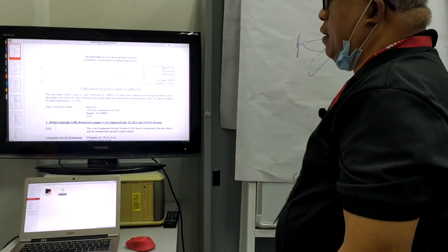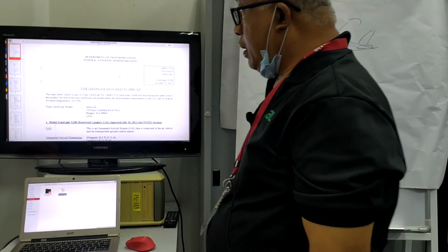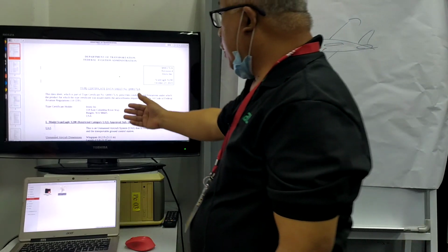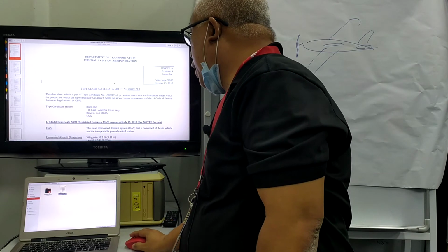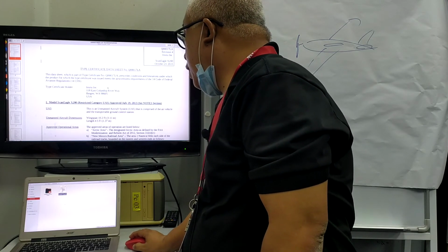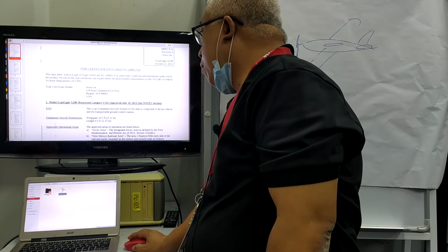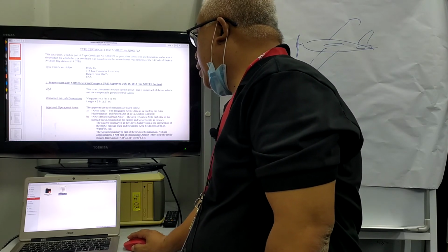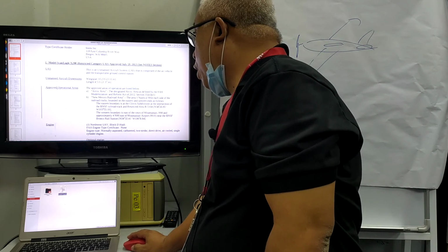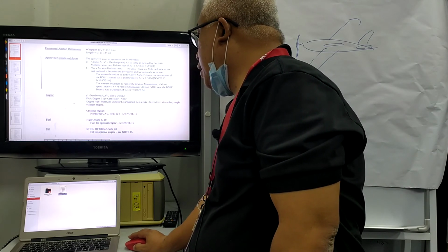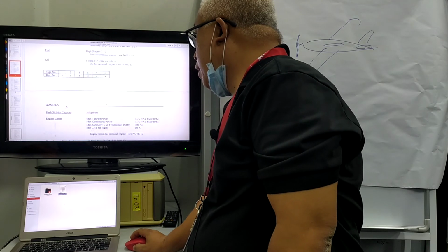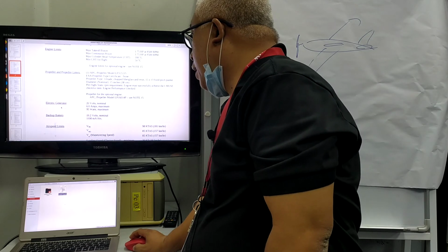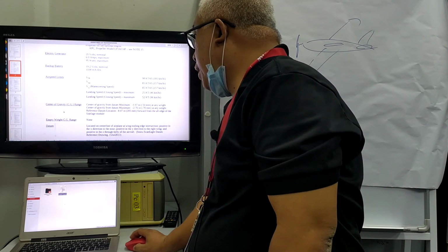Once certified, the special TC is issued. The TC is a prerequisite for the certificate of airworthiness. This is an example where the FAA has issued a TC for the ScanEagle. You can see here, model ScanEagle X200, restricted category, and then unmanned aircraft system, dimension, approved operational area stated there, the engine, fuel, oil, mix capacity, engine limit, propeller, electric generator, backup battery, airspeed, everything is detailed.